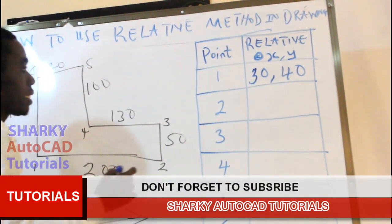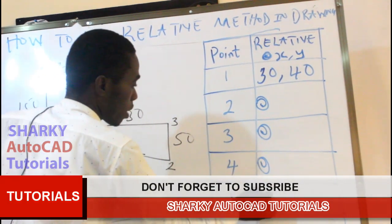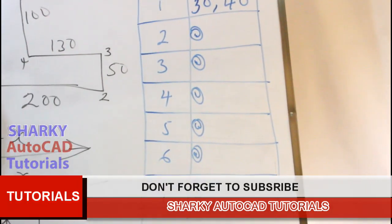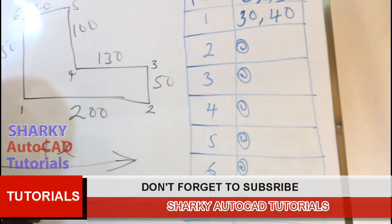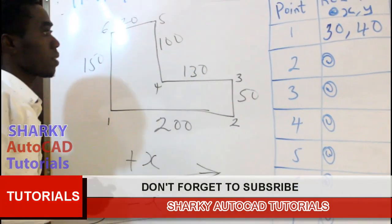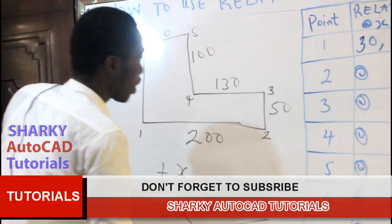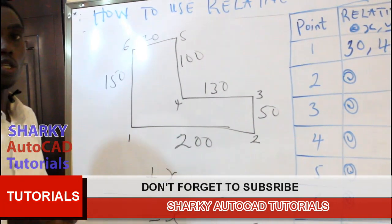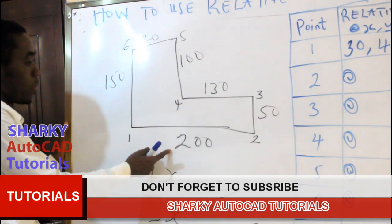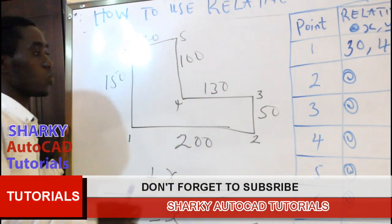Now, relative, you bring the @ symbol throughout, like at yahoo.com. The same symbol, or shift 2. So first of all, you write @ throughout, and then the second point is that the coordinates that you don't have, you write 0. So for example, over here we have x coordinate, but there is no y coordinate, so the y coordinate you write 0.